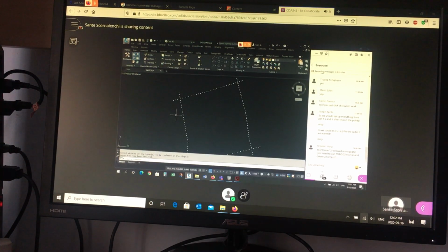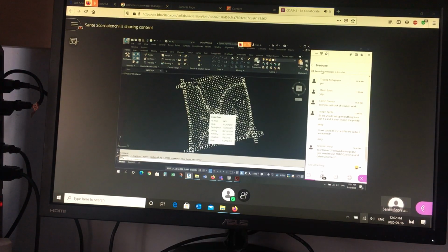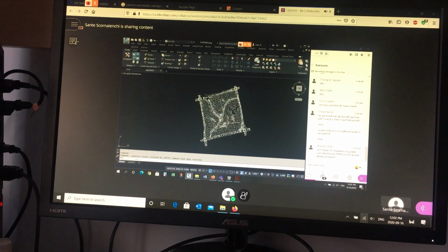It's hard to tell just by looking at the points kind of what the lay of the land is. Right? It'd be nice if I had more than just point data. But besides points, we also have linear features typically, right? Center line of road. It'd be nice if those dots were all connected. Edge of pavement. It'd be nice if those dots were all connected with lines and so on. Okay? Now, usually, not always, but usually a surveyor will provide that information. So if I want to see that information, I could take the time and draw them, right? Turn on my O snaps.